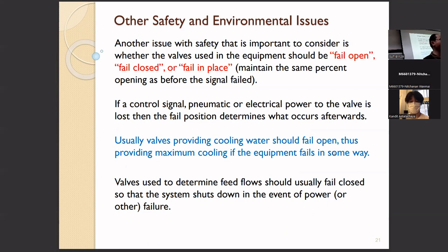If you have some pressure release or some accident, if your system has a pressure higher than the limit, and the system has a safety valve, the safety valve will release automatically. Otherwise, with very high pressure, the reactor will be exposed. You have to be careful if you work with gas.